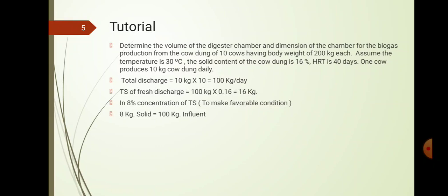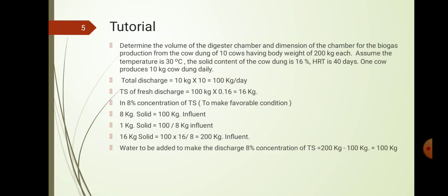So we have to add liquid or influent. Already we have 100 kilogram of discharge, in that 16 kilogram is solid. So how much do we have to add? To make it 8%, the total content should be 200.